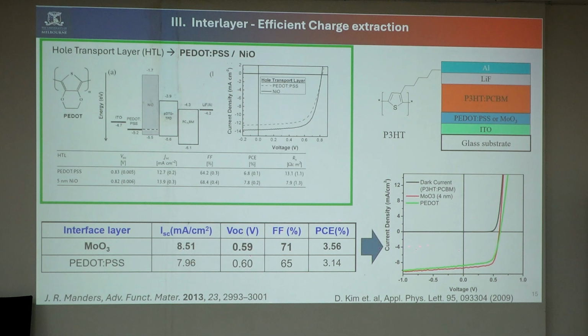The device fill factor is improved, and so is the long-term device performance when you have this type of metal oxide. One of the advantages of using metal oxide is that it is highly stable in temperature. At the same time, it will protect the active layer from degradation, because this metal oxide is already an oxide, so you can't oxidize this material further. Instead, if you use other organic materials, they will oxidize in the air environment. Okay, so we always prefer metal oxide to make the interlayer.